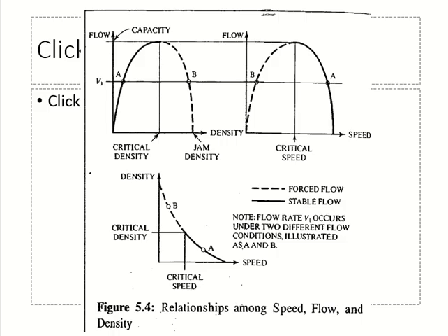We don't call that capacity, because I gave you the example of the parking lot. That is maximum density. Is there a flow there? No. Maximum density will not have maximum flow. What do we call it? We call it jam density. Clear? And there is the maximum speed as well.